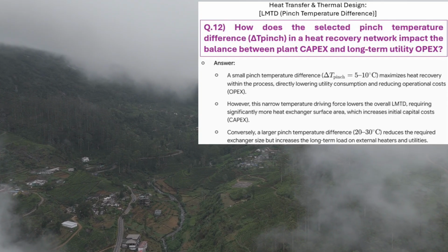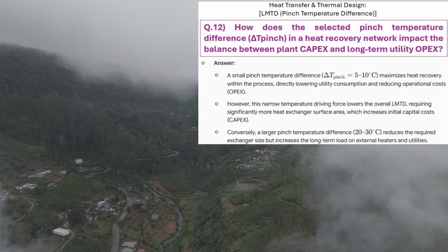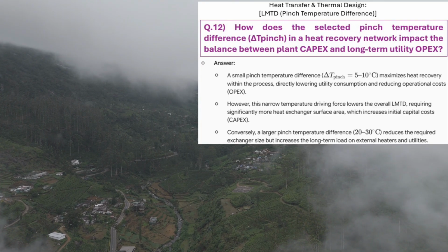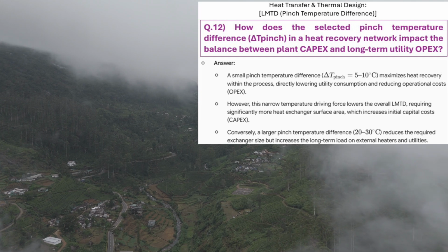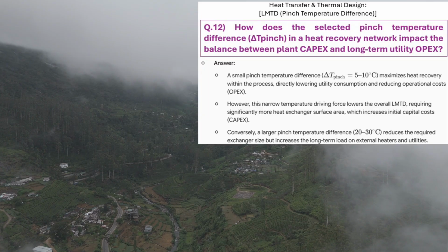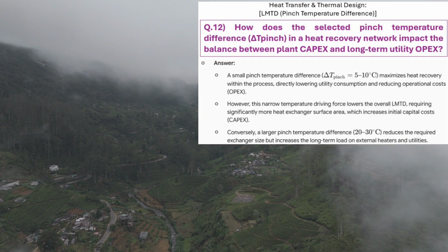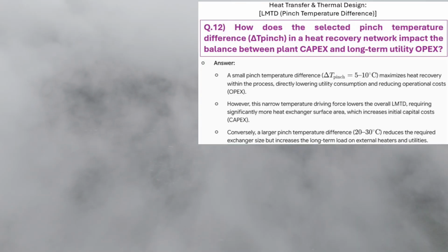I map the thermal connections to identify the cascading thermal impact matrix. I trace exactly how a sudden temperature drop in one isolated exchanger will physically cascade downstream. And the fatal trap is designing strictly for steady state efficiency. Right. Without adding automated bypass controls or trim options, a simple pump trip causes a thermal deficit that ripples sequentially, cooling downstream feeds and knocking the main fractionator off spec.